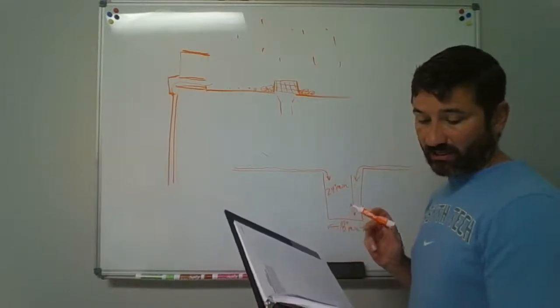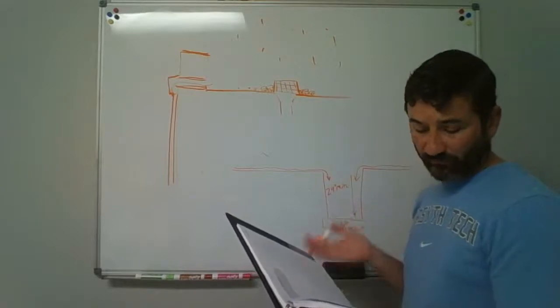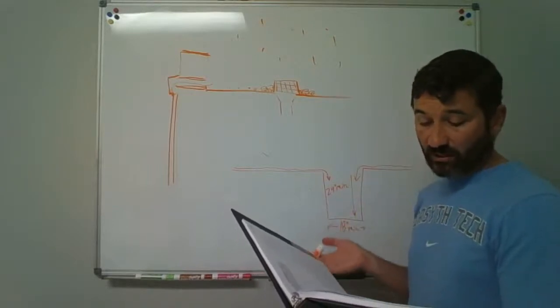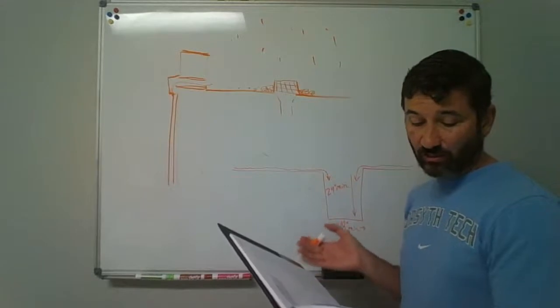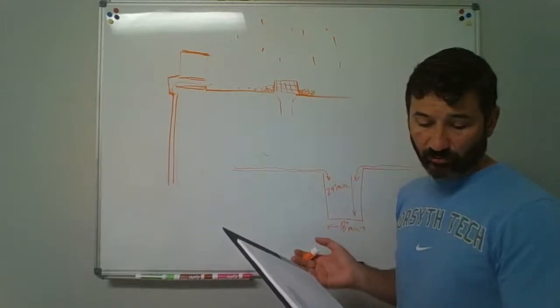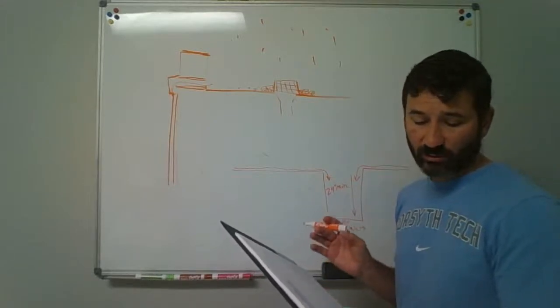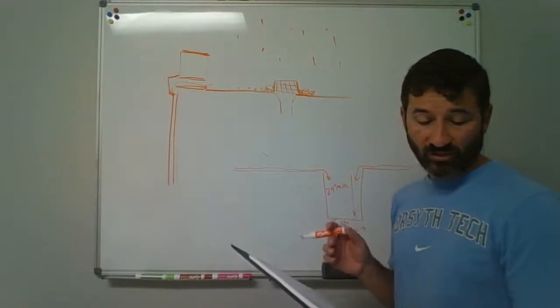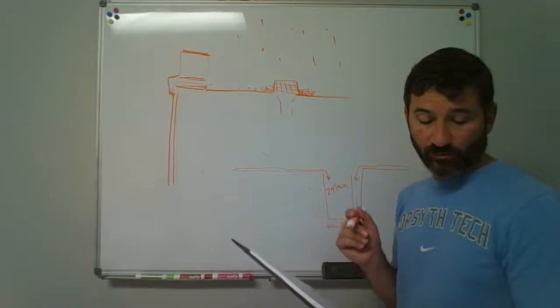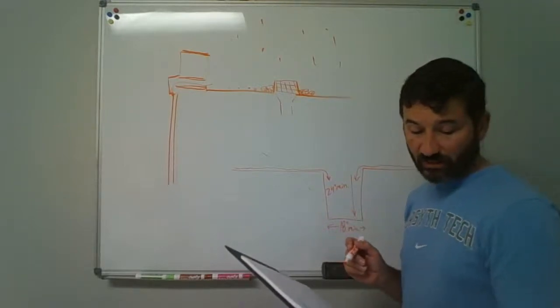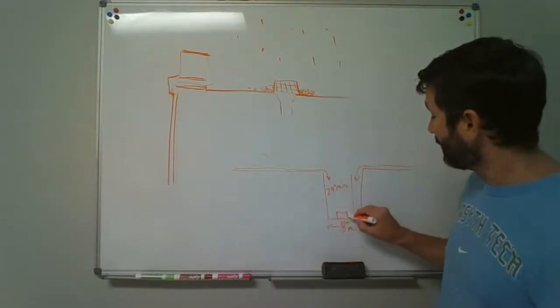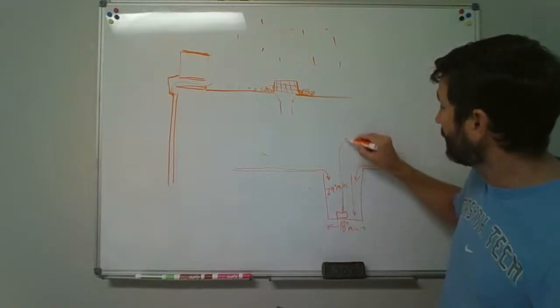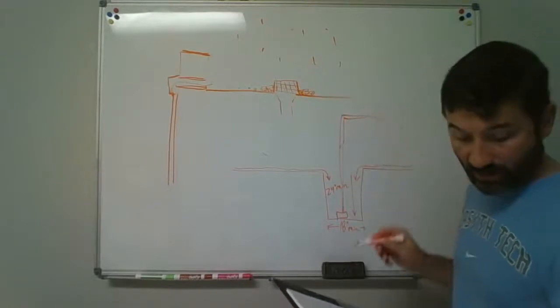The pit should be accessible and located so that the drainage flows by gravity into the pit. The sump pit should be constructed of tile, steel, plastic, cast iron, concrete, or other approved material with a removable cover adequate to support anticipated loads in the area of use. The pit floor should be solid and provide permanent support for the pump. And then it shows you, basically, you're going to have a pump down in here, pump discharge up and out on that. Okay.